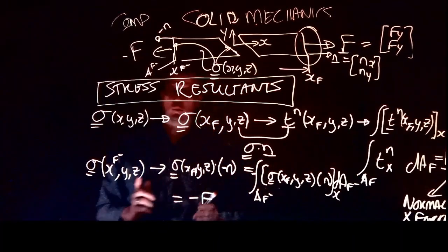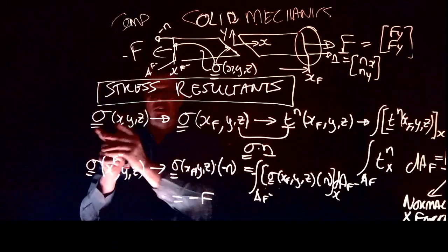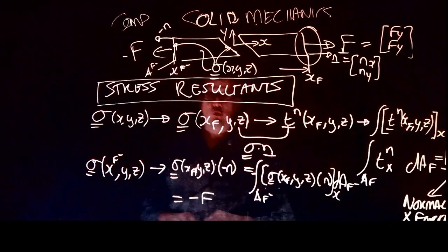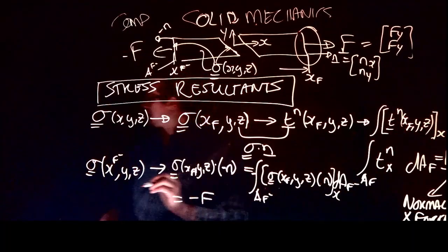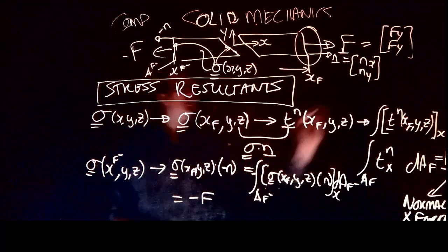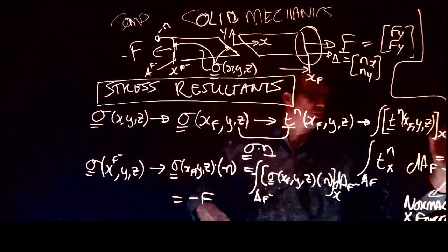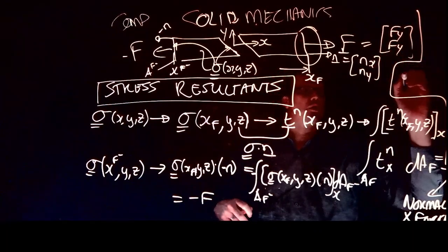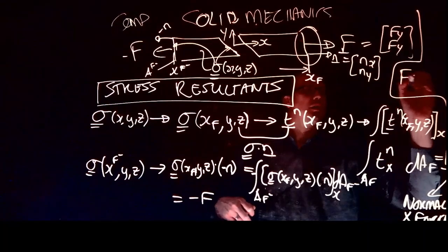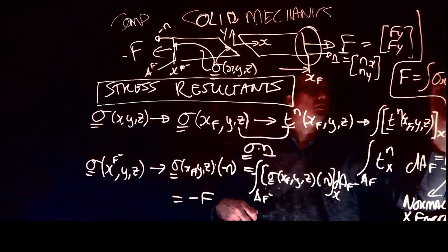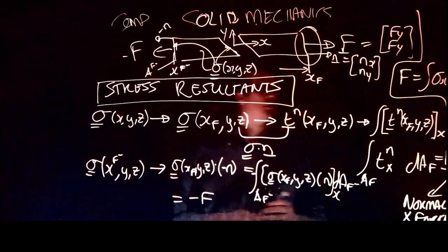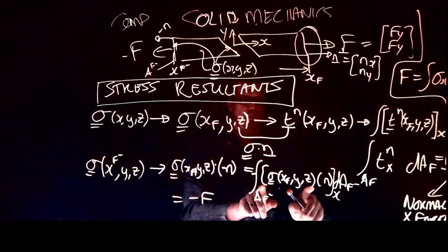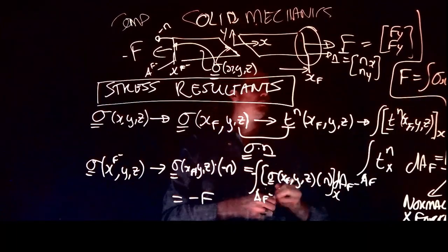And so this is why it's important that when you do this, please follow the steps: stress tensor, traction, from traction to force. Unfortunately, textbooks often do this differently. I just want to warn you not to follow that advice from textbooks. They often write it as, oh, the force is the integral of sigma xx dA, something like that, because essentially sigma xx would be the component that is stored there. But this is not true.